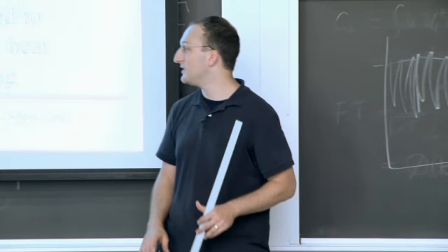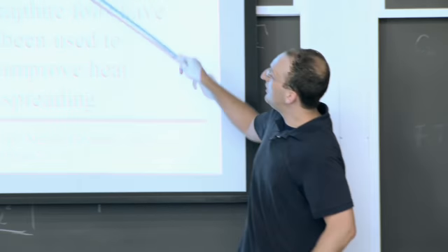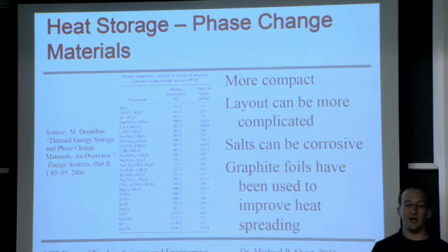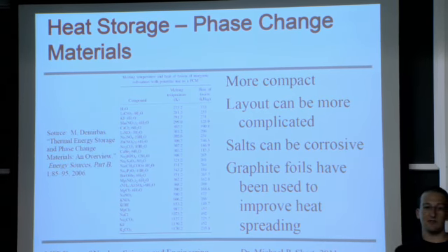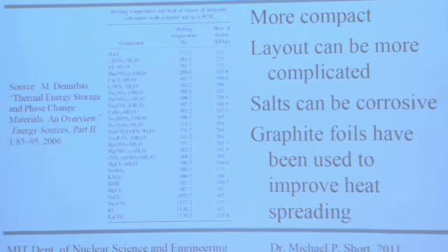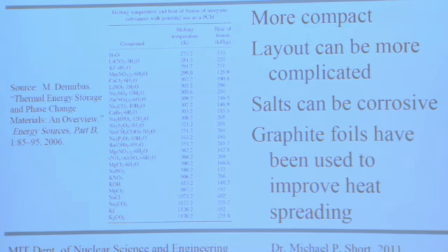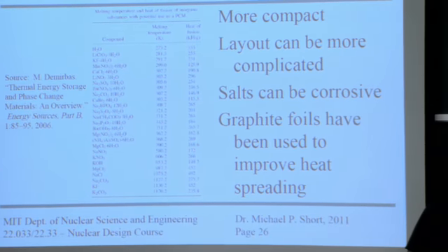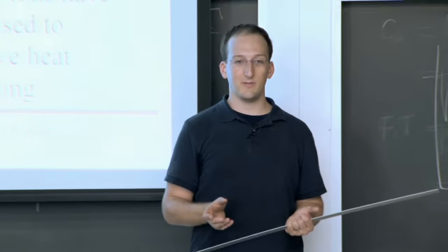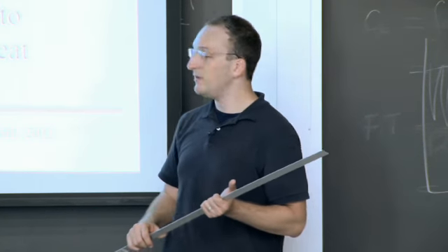As far as phase change materials, all sorts of compounds melt at all sorts of different temperatures, all the way from water up to molten salt, which melt at something like 800 or 900 Celsius. So there are materials out there for whatever you need. You need to look at things like the thermal conductivity, the heat capacity, the heat of fusion, and that'll be able to tell you how much heat can you store in them and how quickly. I would also look and see if there's a density change between the solid and the liquid system to know whether you want to have a nice hard sealed vessel or you want to give it room to expand.